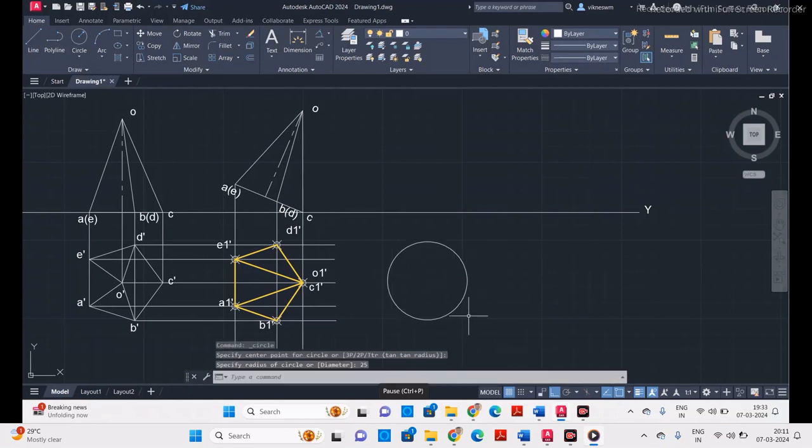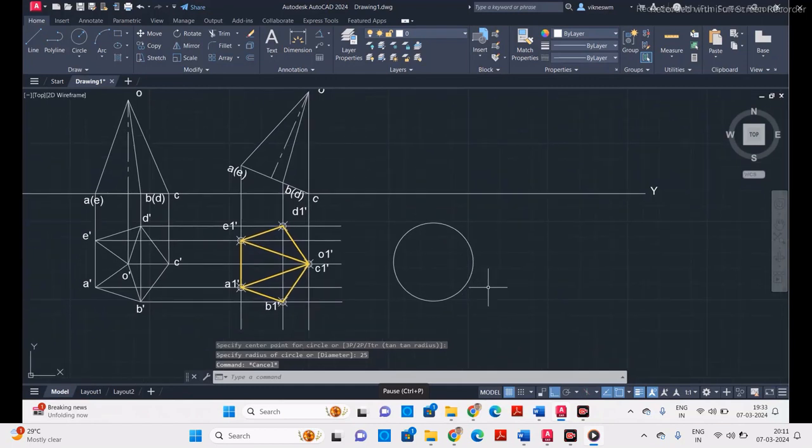Before projecting vertical lines, the circle does not have any defined corners. To create corners, we have to divide the circle into some equal number of parts. First put a line connecting the center of the circle to the base point at the circumference of the circle. So take a line, start from the center of the circle and move towards the base point of the circle.